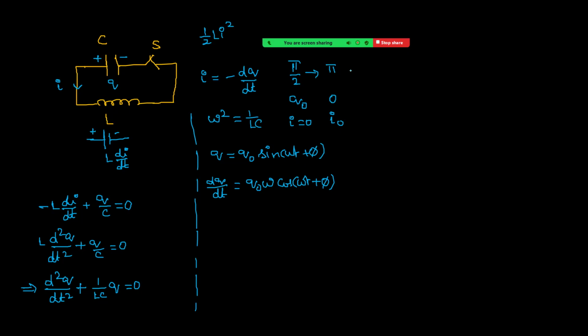Next. Now this omega t plus pi by 2 changes from pi to 3 pi by 2. Means one more 1/4 cycle. Now what happens is charge will be maximum, current will be 0, because cos 3 pi by 2 is 0. This value is max, right? Modulus value. That means now the energy which is stored in the inductor, magnetic potential energy, is completely transferred to the capacitor.